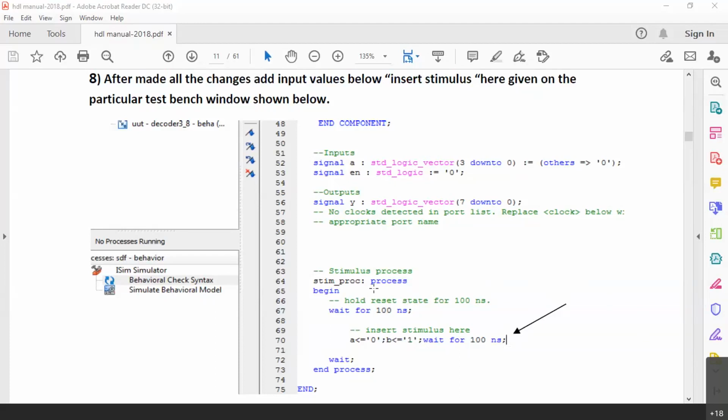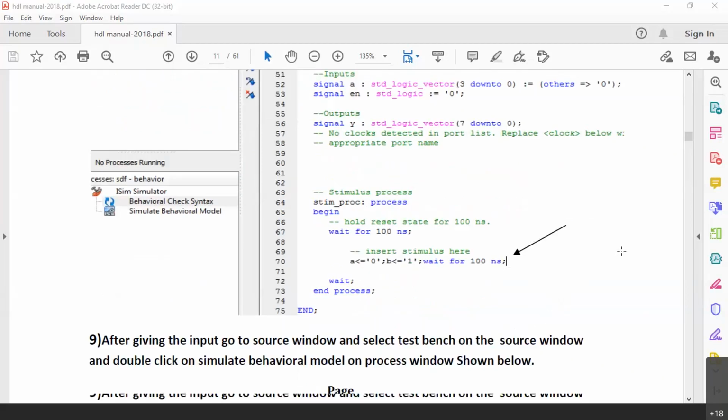That is why you can see in VHDL he has used the word process here. This is where we are telling the simulator that from now on it is sequential. Until then it was all concurrent. Until the simulator encounters this word process, the whole program is concurrent. Now from now on it will be sequential. Similarly in Verilog, until there is a word called always, everything is concurrent. Later on it is going to be sequential. This is important and you will have to understand this.